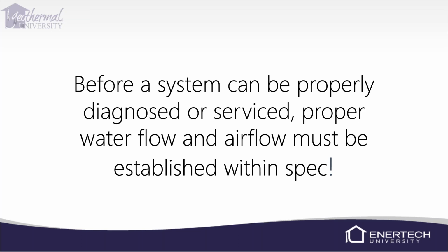With the airflow, it's not really that difficult. If it's got an ECM blower on it, you can look at the ECM board and count the flashes, and that'll tell you how much CFM you're moving. Depending on the tonnage of the unit, you can look in the manual and see how many CFMs you should be moving. On that ECM board, one flash equals 100 CFM.